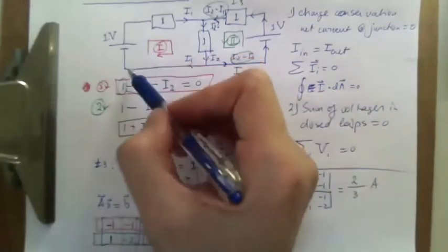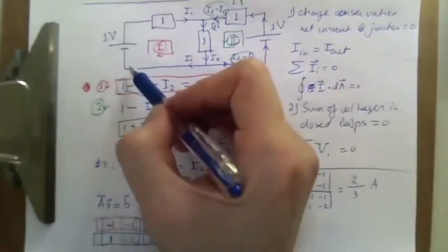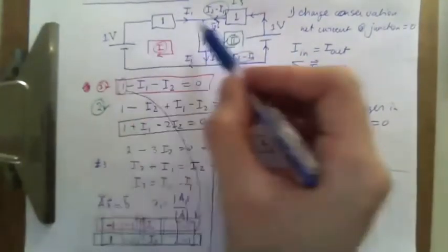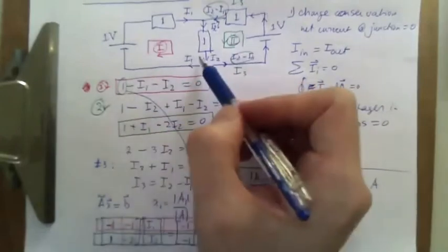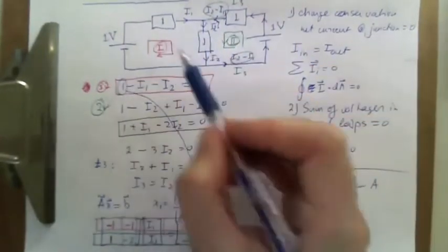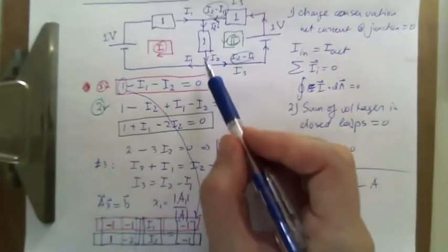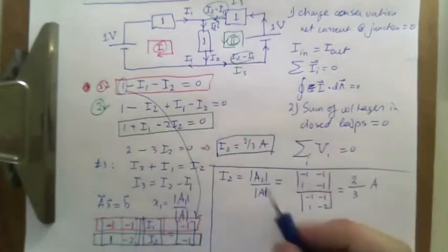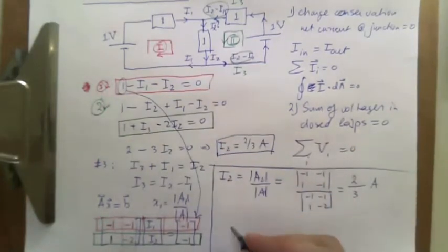And if I go in this loop, you're going to go down plus -1. So there's effectively no voltage increase. And that's fine too, because if the battery's here, there's no voltage increase. So no matter which path you take, the circuit is completely equivalent if you move this and this to the central branch.